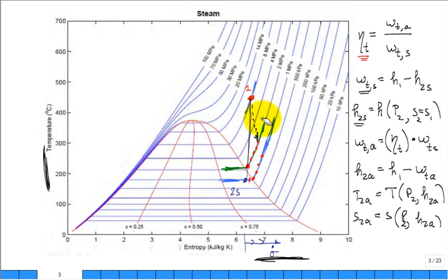I started with the blue and then I went to the green, indicating that sometimes the exit state of a steam turbine could be superheated. That's why I switched and said, now, what happens if you come out at 2 megapascal? You're probably going to come out superheated, even if it's isentropic expansion. So let's get rid of that extra pressure line and just draw it like that. So yes, these 2 actuals all have the same pressure. In this case, it's all 1 megapascal.